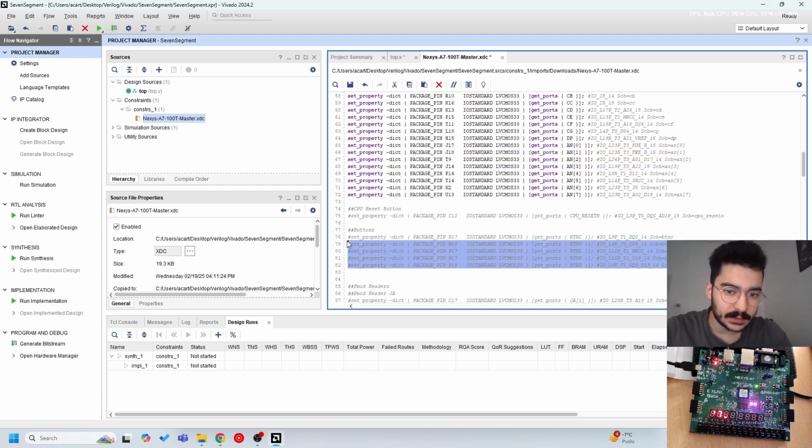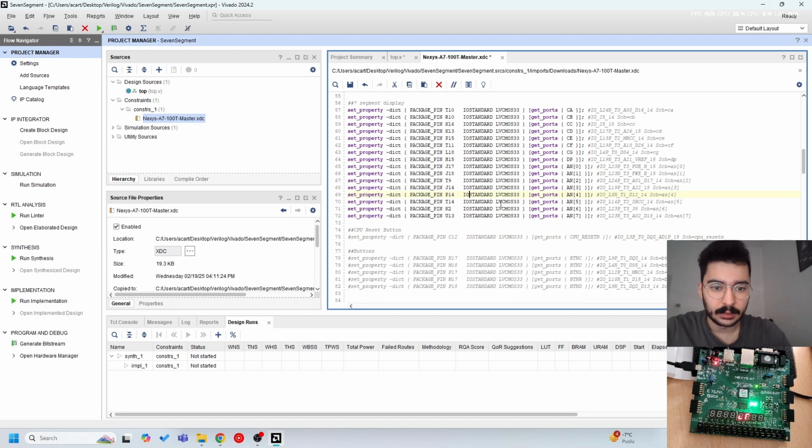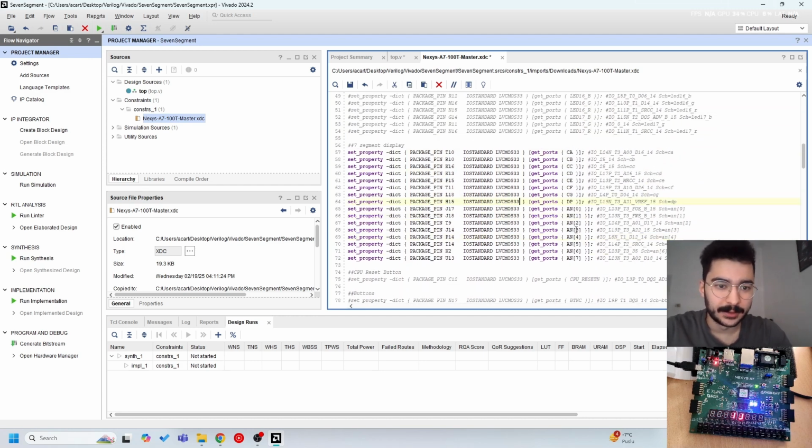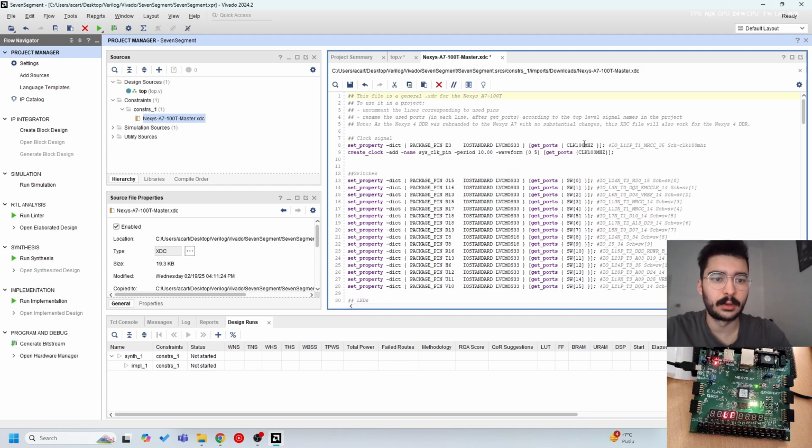I could also use buttons, but I mean, it will be probably overkill for now. These are enough. Okay, so here you can see a bunch of things, so I will go over them very easily. This grade clock is only valid for clock, and for other pins it's not there. And this is for time constraints, and it helps Vivado when you synthesize your design. It helps Vivado to satisfy Fmax, the maximum frequency conditions, and checks that it can satisfy those constraints.